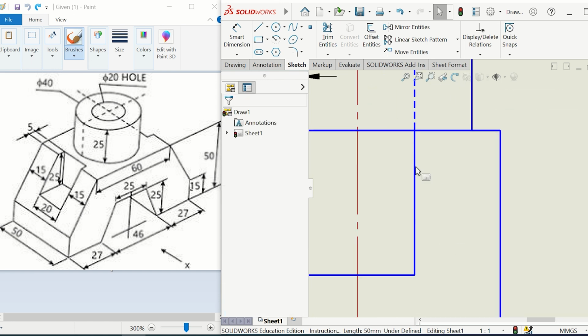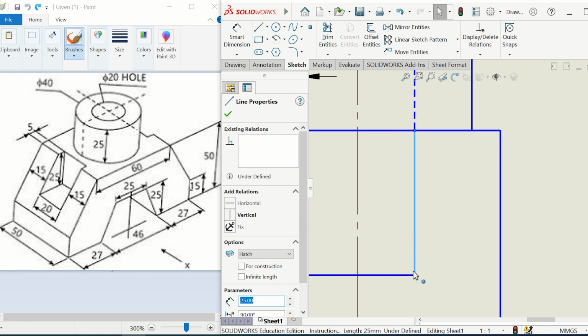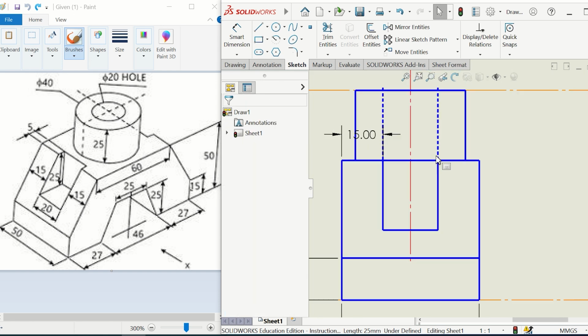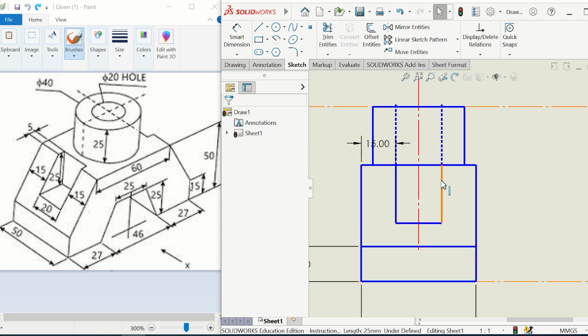On top of it, there's a nut, which is this one, a continuous line. And this obscures the hidden line, and a dashed line overlapped by a continuous line is equal to a continuous line. From where does this continuous line come from? It comes from this visible line and this visible line. So this is what it is now. This is hidden, overlapped here by visible, hidden, overlapped by visible, and this is how it looks.